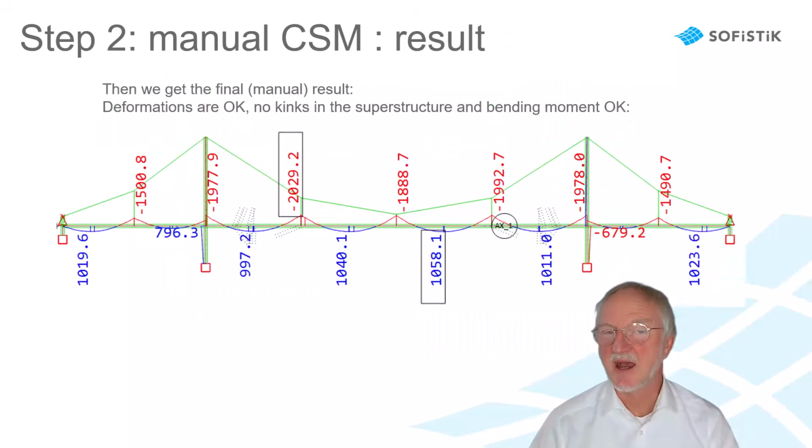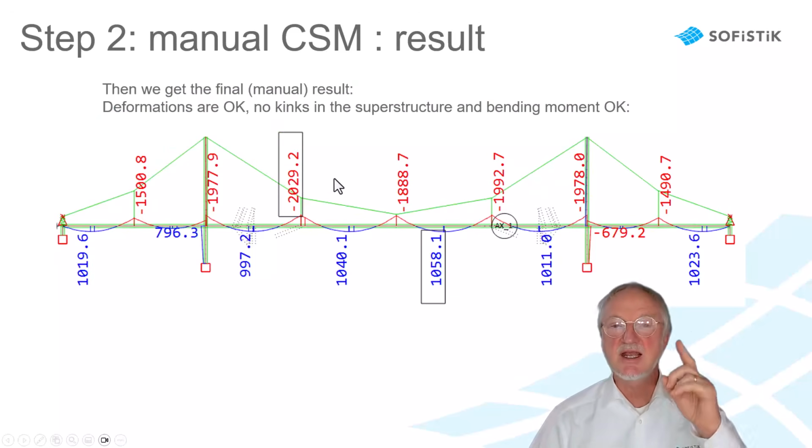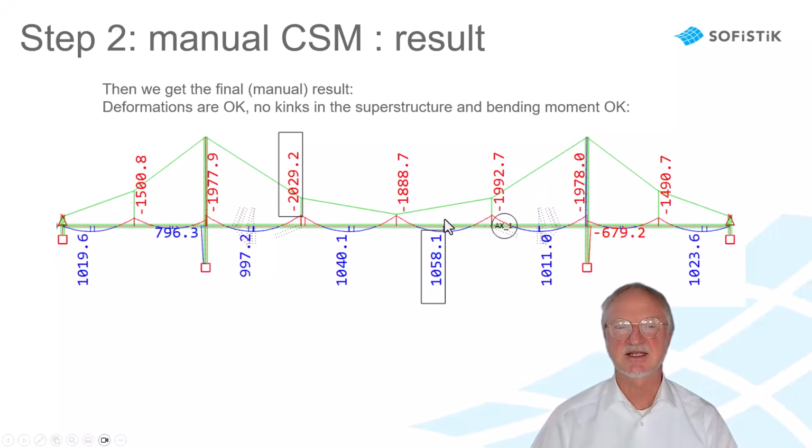Now we come to our final traffic opening stage, including the staged analysis, and you see we have a very nice balanced bending moment in the superstructure. The deformation of the superstructure is nearly 0, and with this we can open our bridge.